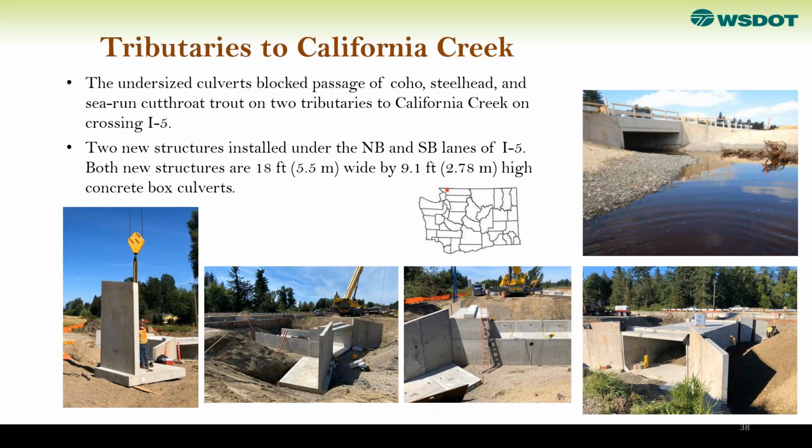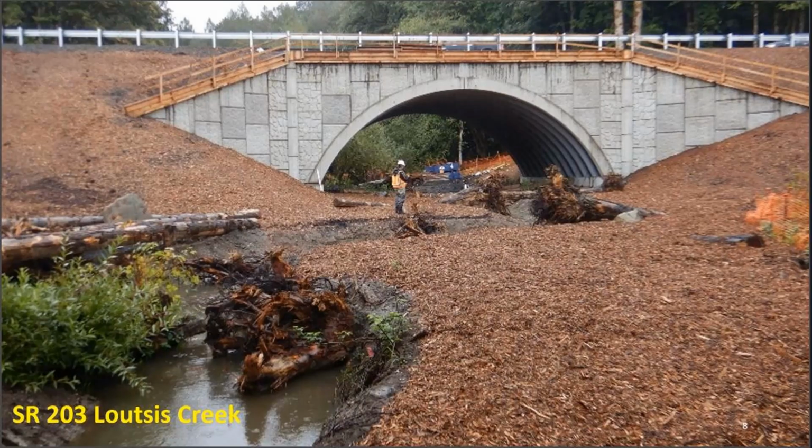I can mention Lutsis Creek on that. As I showed in the pictures, it went from about a 4-foot diameter pipe, I believe, up to a 50-foot wide opening. And a lot of the size of the opening was driven by making sure we could accommodate an upstream floodplain that had been largely neglected. So I don't think there's any direct correlation there, but again, we're careful to make sure that's considered when we determine the width of the crossing we need to put at any given location.